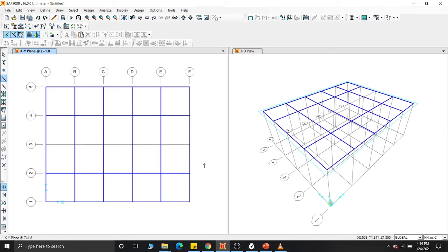And the next main point is the support conditions. So usually in a bridge, we know that there will be thermal contractions and expansions. So we have to allow some movement in the horizontal direction in a bridge. If not, it will impose additional compressive stresses on the bridge that can lead to cracks and other issues.